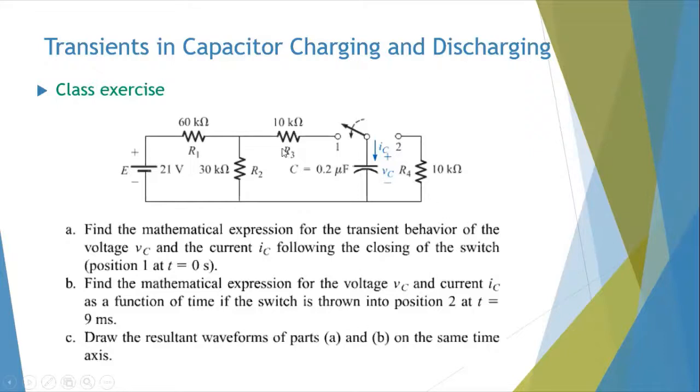So a bit more complicated here, where you have a circuit with a few more elements, and you have a capacitor there. So the charging phase is not straightforward. You have a capacitor here, fine, but what value would you use for the resistance? Because you have to get the time constant, which is RC. The C is 0.2 microfarad, but what about R?